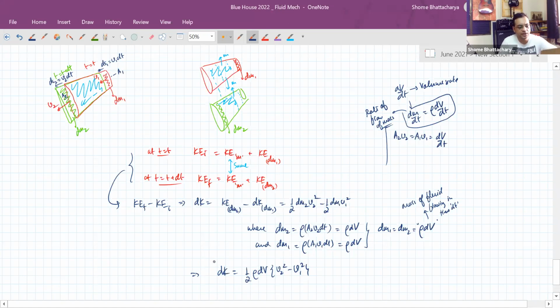As I was telling you, each of the terms will come in terms of the individual parameters. The work done term had come in terms of the pressure difference. The change in kinetic energy term is coming in terms of some relation of v2 and v1, and as it turns out, that relationship is the difference of v2 square and v1 square. And like that, we'll see the third term, the potential energy term, will come in terms of height difference. So when we relate the three terms in the work energy equation, we'll get a relationship between v square, pressure P, and height h.